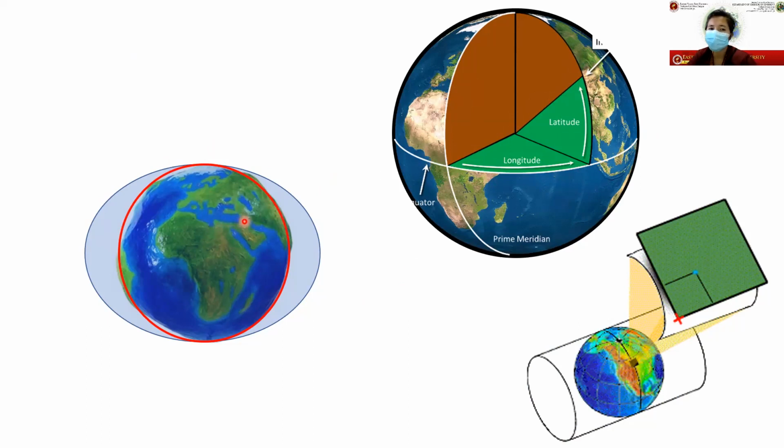As we all know, the Earth is not a perfect circle, not a perfect spheroid, and not a perfect ellipsoid. So to make sure that all of the surveys around the Earth are similar, we introduced this system we call the ellipsoid. We projected an imaginary shape of the Earth, which is the ellipsoid, and we created some parameters which approximate a certain position on Earth. So we have the A, the semi-major axis, the semi-minor axis, and the flattening of the surface of Earth.